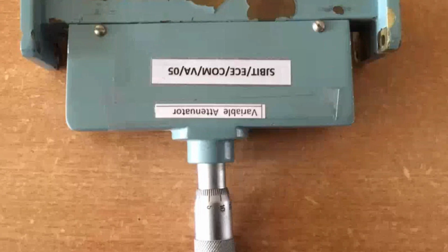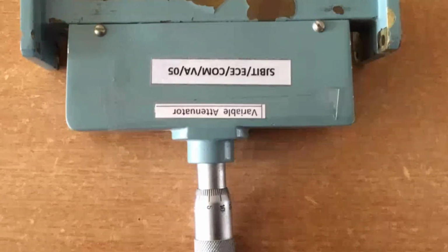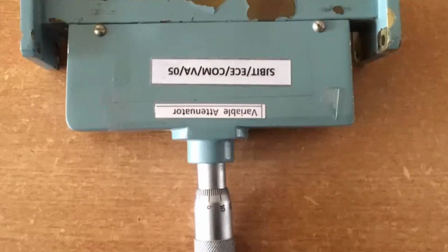That meter knob is attached to a rotary type of disc, and whenever I rotate this knob, the flip or the vane can move inside and backside, in forward direction and backward direction. Whenever it is rotated clockwise, it moves in inward direction, and whenever it is rotated anti-clockwise, it moves back in outward position. So depending upon the inward and outward position, the level of attenuation can be varied.